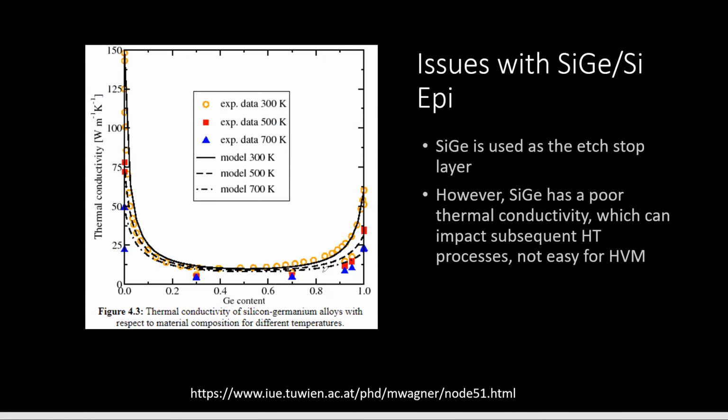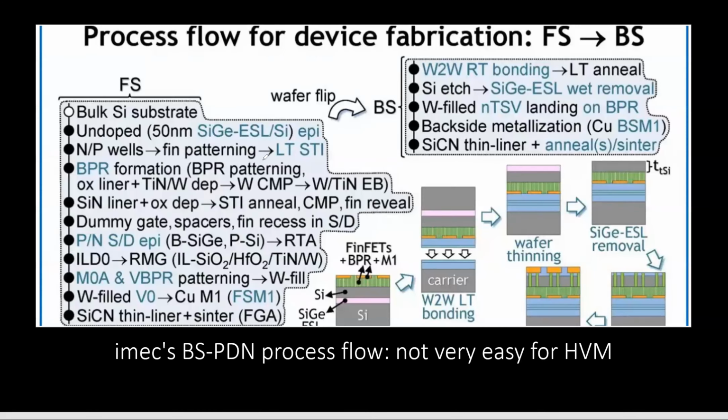If you look at this thermal conductivity graph on the left, you will see that the thermal conductivity drops like a rock. It's a bathtub curve. So the silicon germanium that you use in here is at least 30%, to make it effective. Because you need to etch-stop somewhere. The material cannot say I'm using 1%. Then it's meaningless, you will not stop. It has to be an etch stop layer. The germanium content should be as high as possible. Let's just assume 30% for the argument's sake.